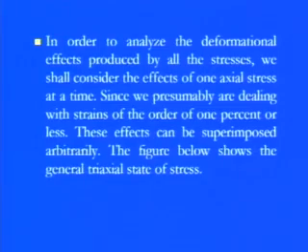So in order to analyze the deformational effects produced by all the stresses, we shall consider the effects of one axial stress at a time. Since we are presumably dealing with strains of the order of 1% or even less, we have to be very careful about whether we are going beyond a certain point or not. If we are dealing with small limits of strains and stresses, the elastic limits are well stabilized and Hooke's law is valid for this kind of relationship.